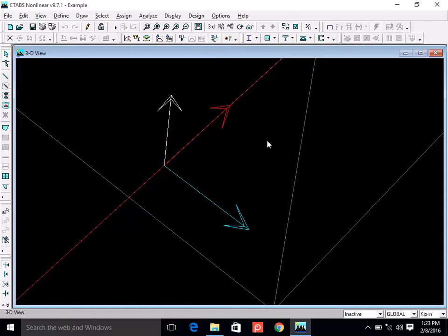Okay, when you bend this beam like this, or when gravity load bends this beam like this, bending is about this axis, and this is the out of the plane axis. So remember that the bending moment due to the gravity load is always about the out of the plane axis. Okay, this is for beams. Either it is like this, sagging, or it is like this, which is hogging. All the time it is about the out of the plane axis. Okay. So we shall read shear along axis 2 and moment about axis 3, along and about.